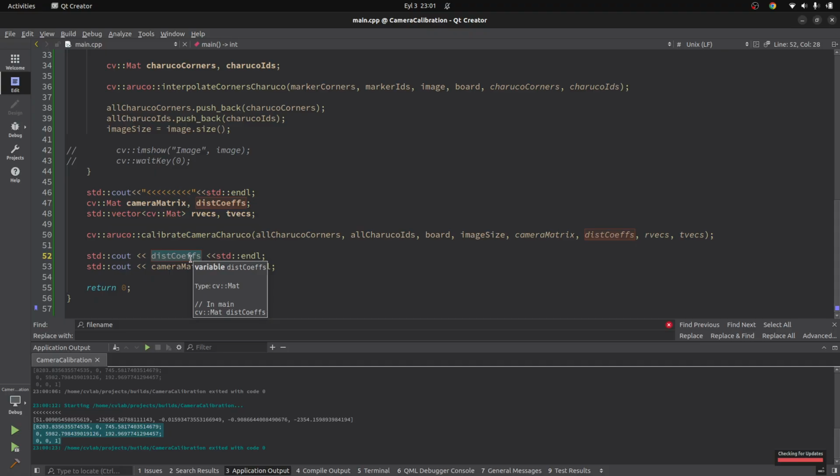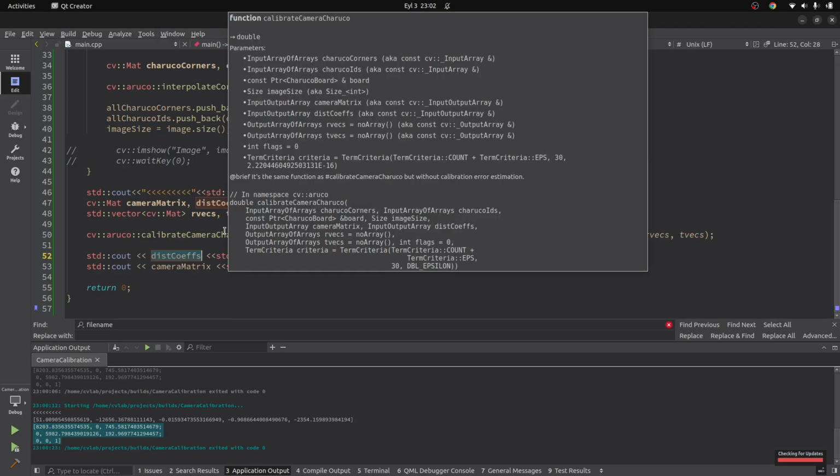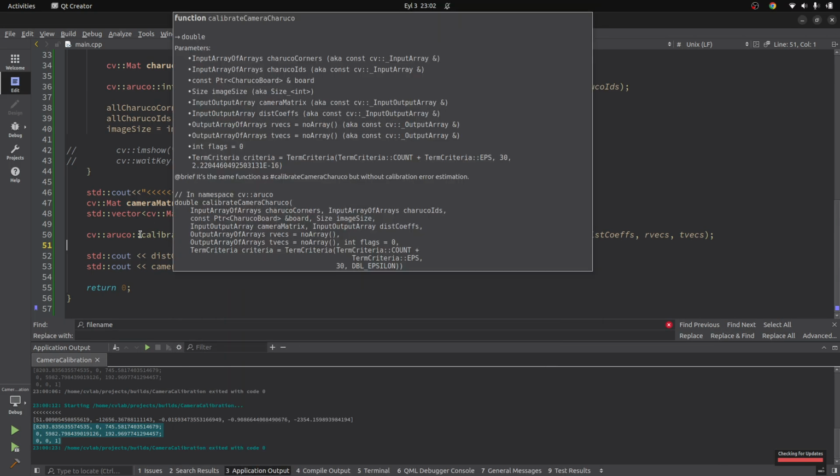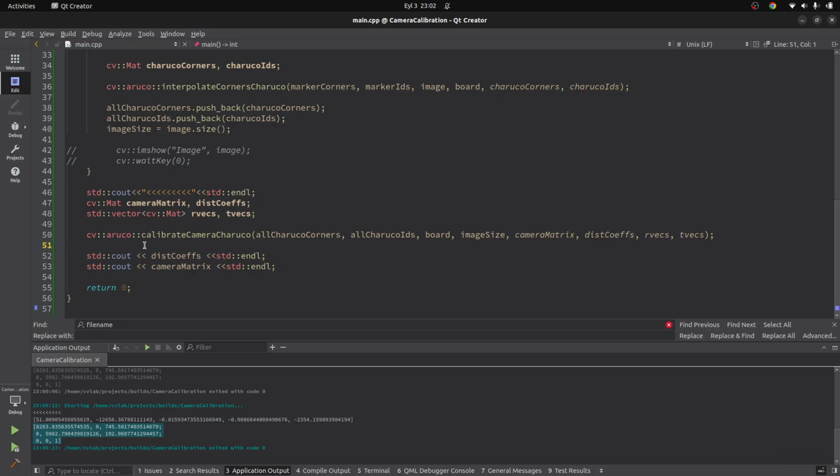But as I said again, calibration is very important if you are dealing with accurate measurement, let's say 3D coordinate measuring in a real world application. If something goes wrong in your application, most probably at the beginning you didn't calibrate your cameras properly. Also, you don't need to do this calibration just one time, because calibration can be broken.